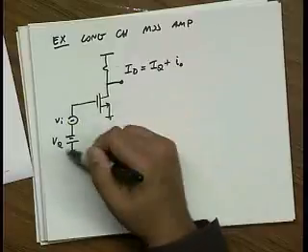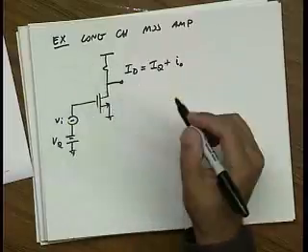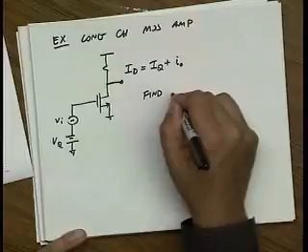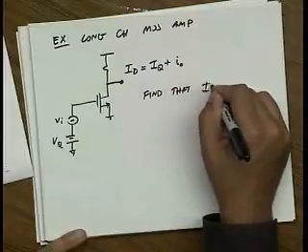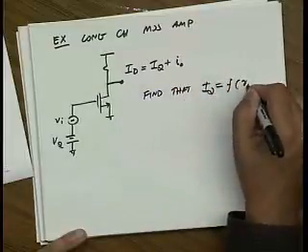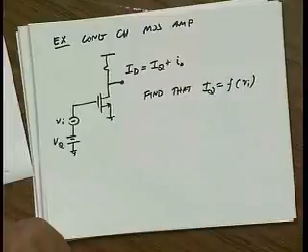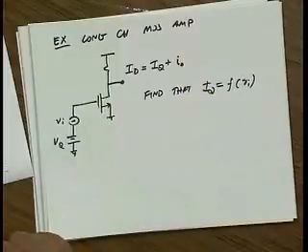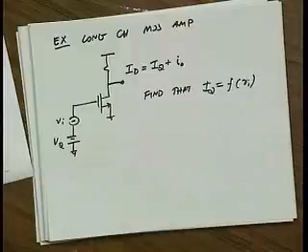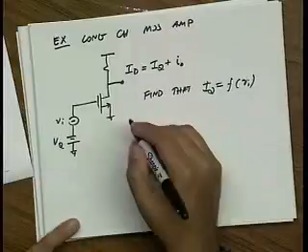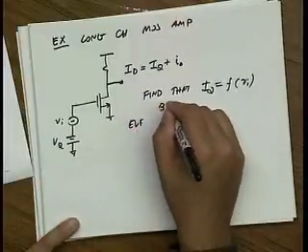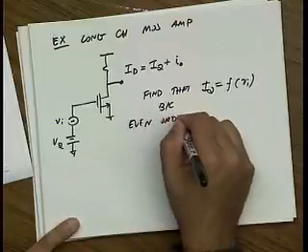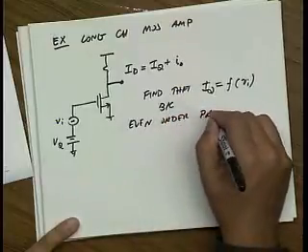If I had just a simple system like this, I would find that IQ is a function of the input. So I couldn't just simply take it out of the equations like I usually do. Right? Remember, cosine squared is 1 plus cosine at twice the frequency. So that one term generates DC. So even order produces DC.